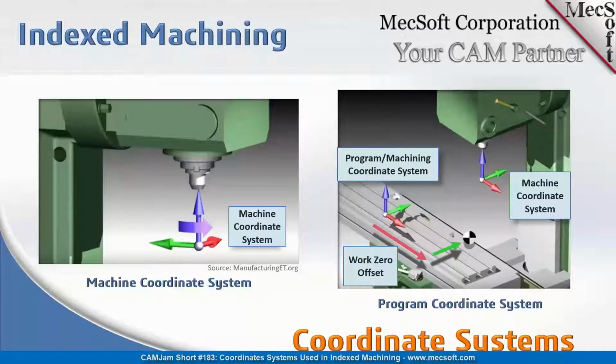Typically, the 0 is when all the motors are zeroed out, where the head comes to rest, and that's where most machine tools would define their machine coordinate system 0. And then the x and y and z are really up to the machine tool vendor. Each of them defines it differently, but what I've seen in the industry mostly, as you stand looking at the machine tool for 3-axis machines anyway, is the x-axis is going towards your right, and then the y-axis is going into the machine. So that's typically how it is defined.